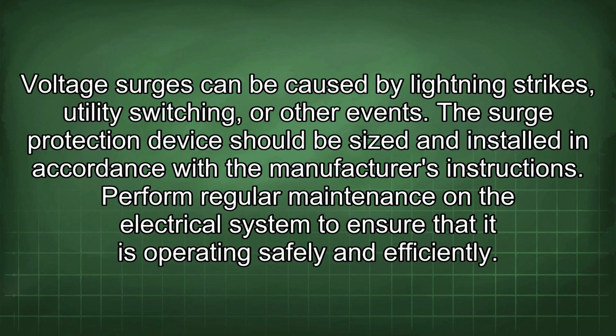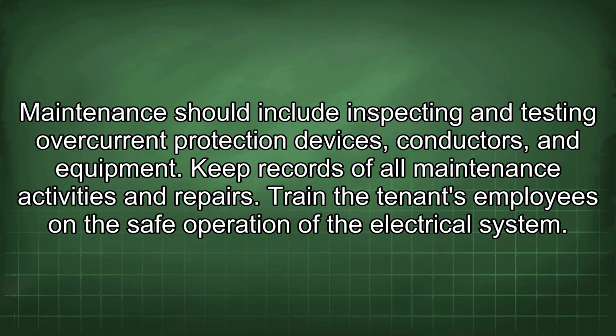Perform regular maintenance on the electrical system to ensure that it is operating safely and efficiently. Maintenance should include inspecting and testing overcurrent protection devices, conductors, and equipment. Keep records of all maintenance activities and repairs.